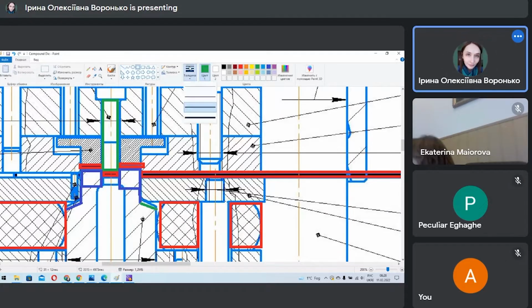If we imagine that here, let it be seen, here it will be the punch for the future outer contour of the ready part. That's why in one stamping process, we give this part two different options. One time it's a punch, another time it's a die. And this element we call with a double name, punch die.